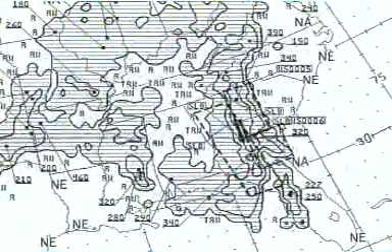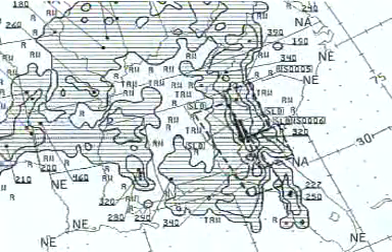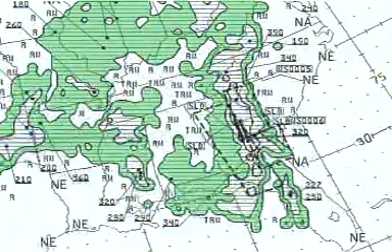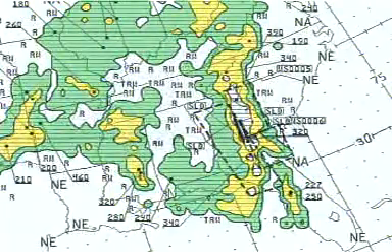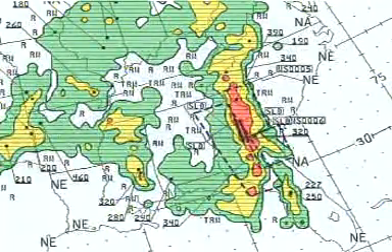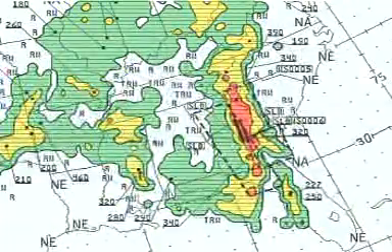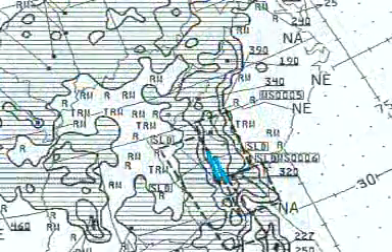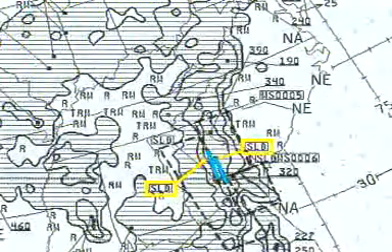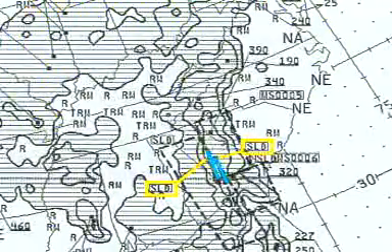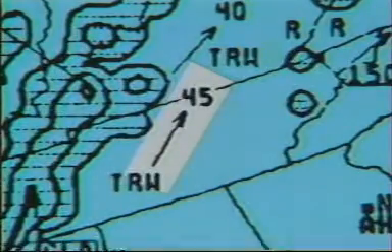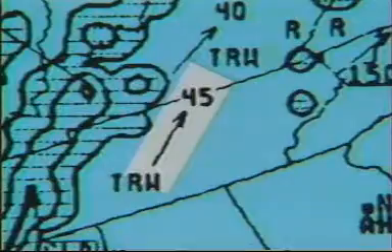The strength of the echo returns is shown by solid lines surrounding shaded areas. The outermost line indicates precipitation that is light to moderate. A second line within the echo depicts heavy to very heavy precipitation, while a third line shows where intense to extreme precipitation exists. A solid single line shows a line of echoes with the boxed SLD indicating that the echo coverage is 0.8 or greater along the line. The direction of movement of an individual cell is indicated by an arrow. The speed, 45 knots, is shown at the point of the arrow.